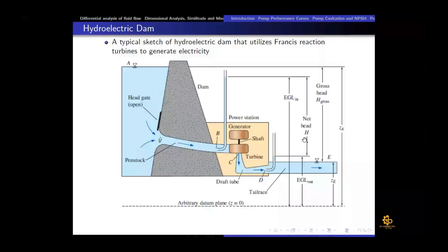It is the difference in the manometer readings at the inlet and outlet of the turbine. So where is the rest of the head? That is consumed by the frictional losses, right? Because the water has to flow from this reservoir to the turbine through the penstock, there would be viscous losses, like we discussed in chapter number 8 when we discussed internal flows. Those losses are unavoidable, so we have to live with that.